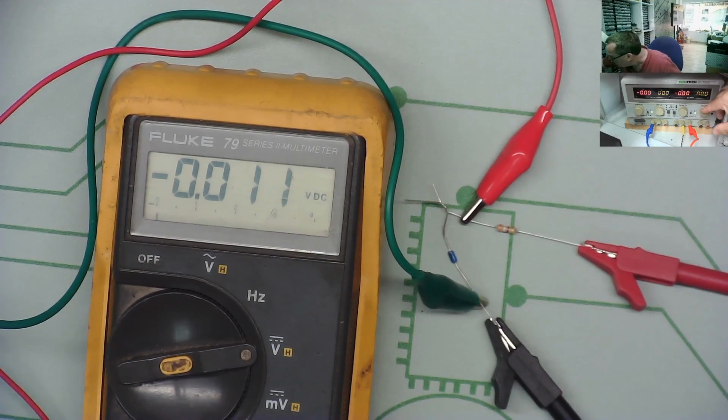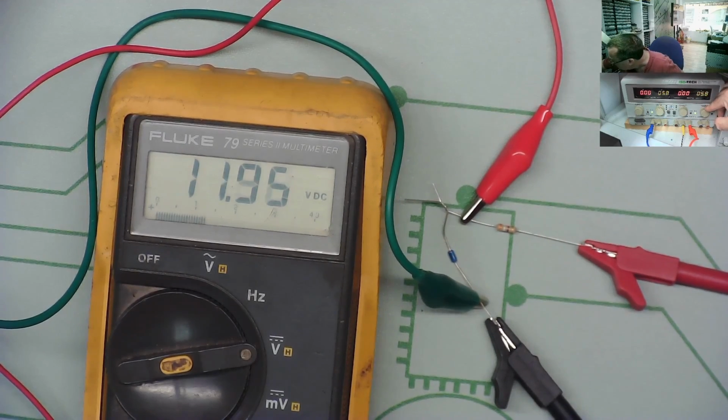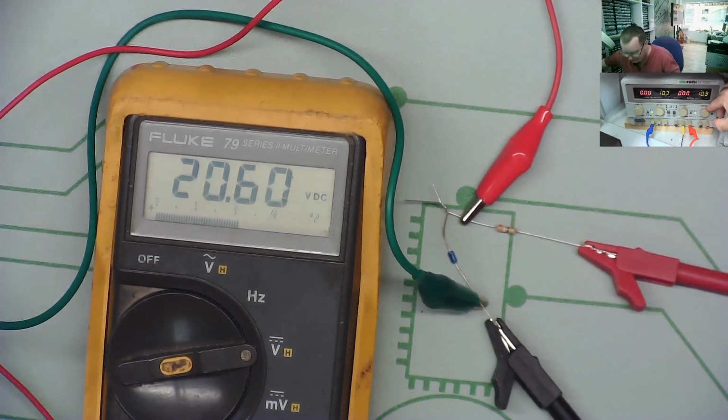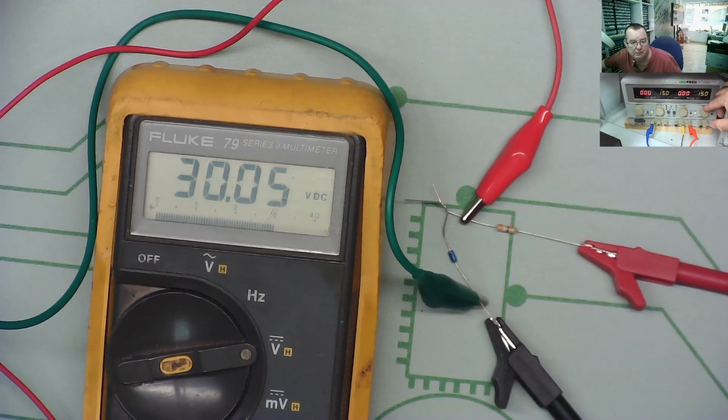So I'll increase the voltage on my supply. Now you'll notice that this is reading 4.5, 4.5, and this says 9. So the output voltage is the sum of the 2. If, for example, we go up to 10 on here, that will give us 20 volts. This Diac is a 33 volt Diac, I think. So basically nothing will happen. The voltage here will match the voltage coming out of the power supply until we reach about 33 volts. We have 30 volts now, and let's go up a little bit more.